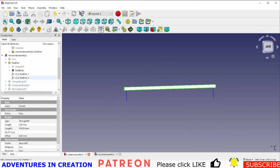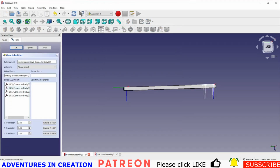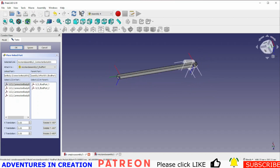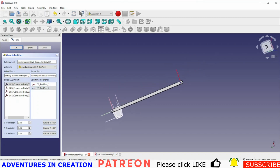Okay, so the next piece I want to bring in is one of these connector bodies. Same thing: we're going to say import a part, and I'm going to say connector body, say insert. The connector body I can connect with one of my LCSs, and I'm going to connect it to my rod part assembly. I can put it either on that end or this end, and you can see which hole is actually connected there.